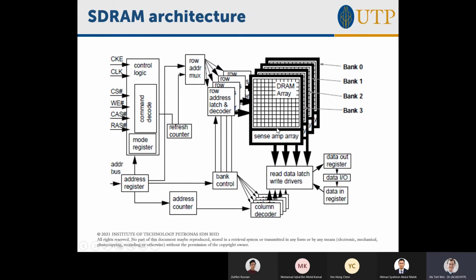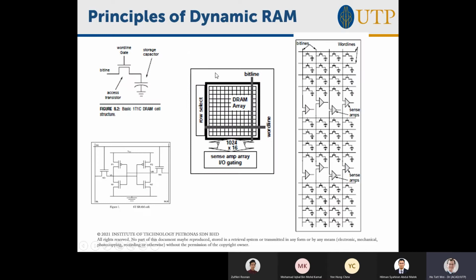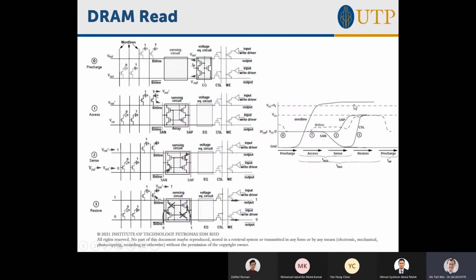It's a bit complex, and it's going to sequence a bunch of commands. It's not just that you put the address and you get the data. When you interface with modern SDRAM, you are actually sending it a bunch of commands. It's quite similar to what you would do on a bus with a processor, or with a sensor. Let's say you've done I2C or SPI programming: you send a command and then you get a response. You're going to be doing that with the SDRAM. You have to design that circuit, so I have to go through all these things so you understand.